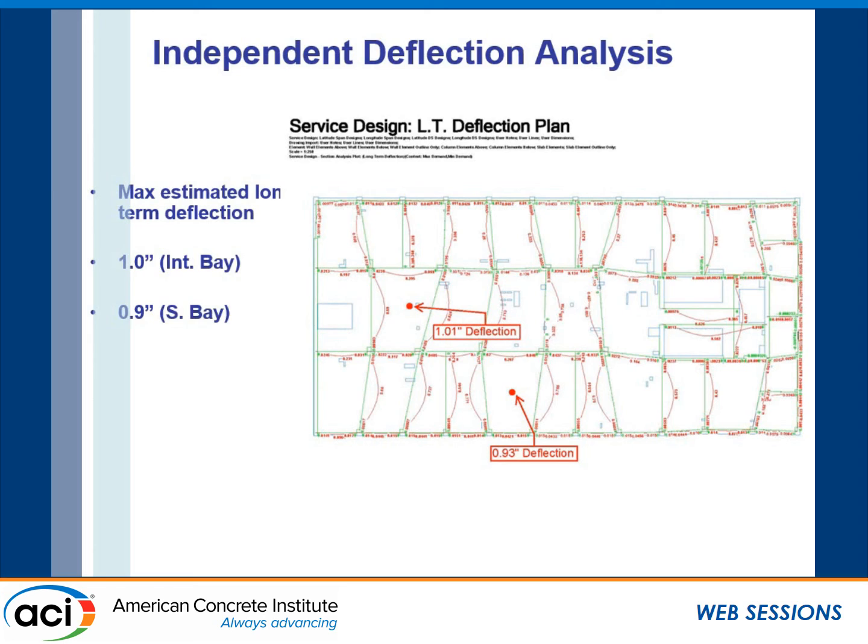There's a lot of variability in deflection design, and so there's a lot of uncertainty with the material, and with tolerance and bar placement and whatnot that could result in the differences. And also, of course, you've got the nonlinear creep, shortening, and cracking that play into this ambiguity, and also the methodology of the different software packages, whether you have a time-dependent analysis or not.